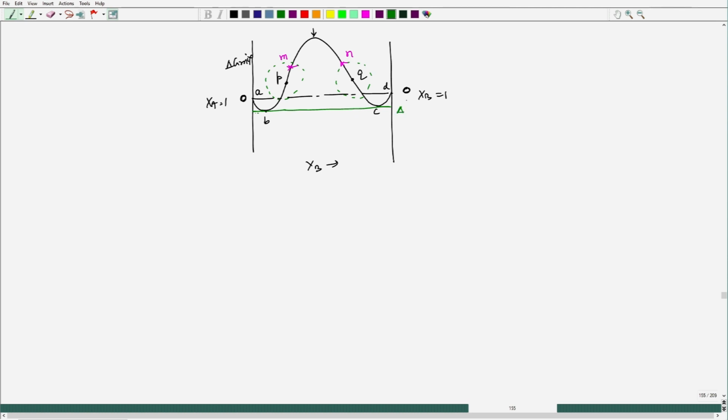And here we have this particular portion, which is delta G bar m of component B at composition B, delta G bar m of component B at composition C. So, this particular portion is basically delta G bar m of A at composition B, delta G bar m of A at composition C. Okay. That common tangent rule we apply.